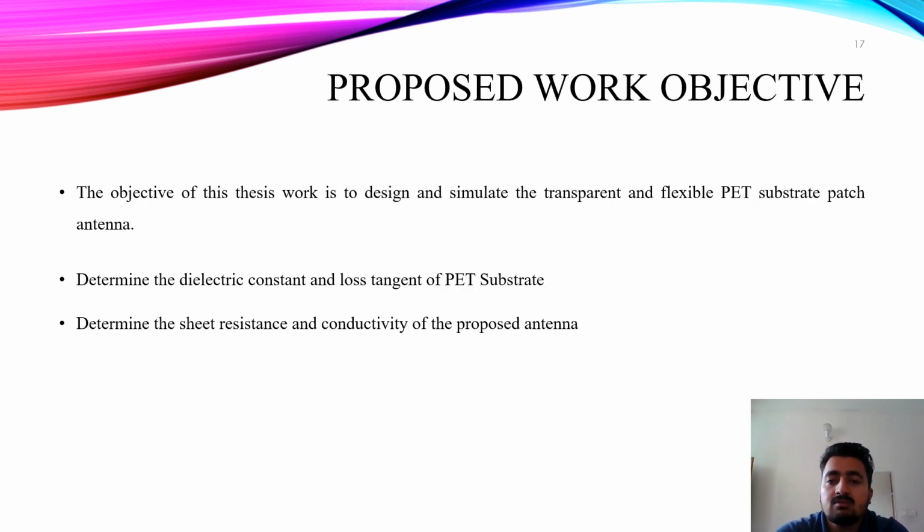This is our proposed work objective, and the objective of this work is to design and simulate a transparent flexible PET substrate patch antenna, determining the dielectric constant and loss tangent of the PET substrate using ring resonator test, and determining the sheet resistance and conductivity of the proposed antenna using four probe technique.